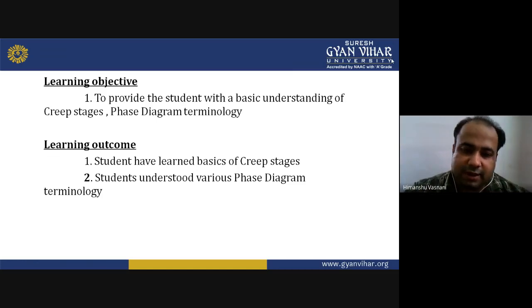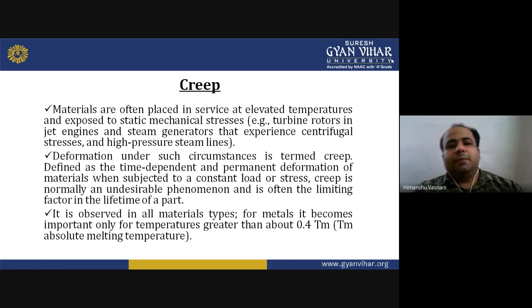So let us start with today's lecture. Creep. Materials are often placed in service at elevated temperatures and exposed to static mechanical stresses. Examples are turbine rotors in jet engines and steam generators that experience centrifugal stresses, and high pressure steam lines.